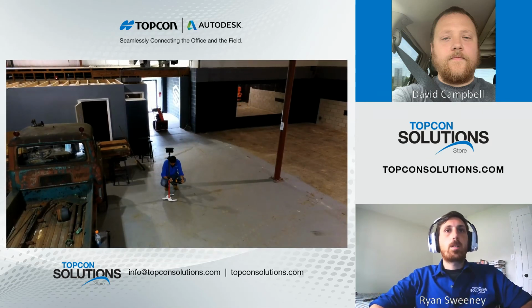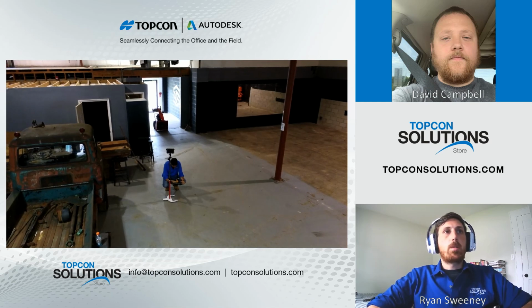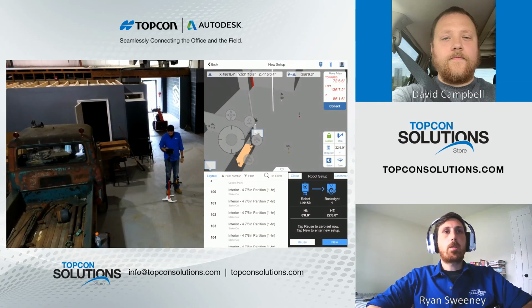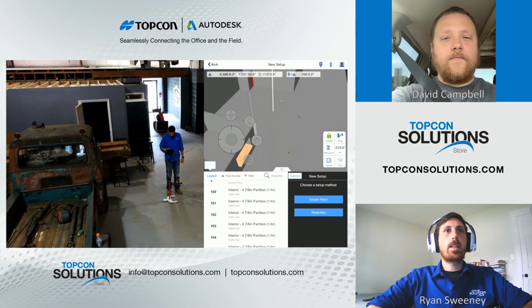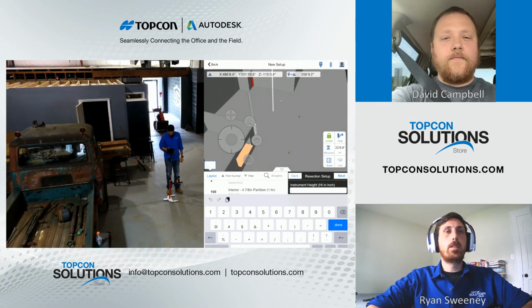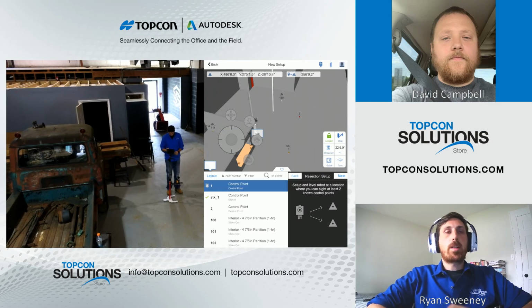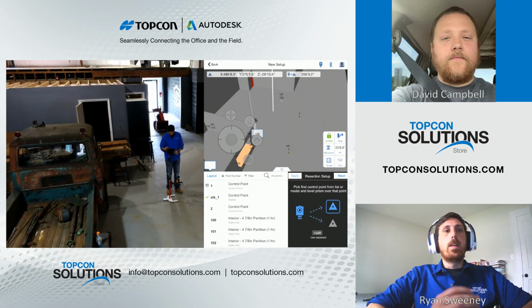Okay, now that we're all connected, we're going to go and set up our total station. So I walked right on over to our first point. I know where the first control point is that I wanted to start with, and we're going to go line up that XY positioner right on the point. Now we're going to set up our total station height, our target height, and now we're going to go and shoot our first control point. We're already set up on it, and we're going to hit next.